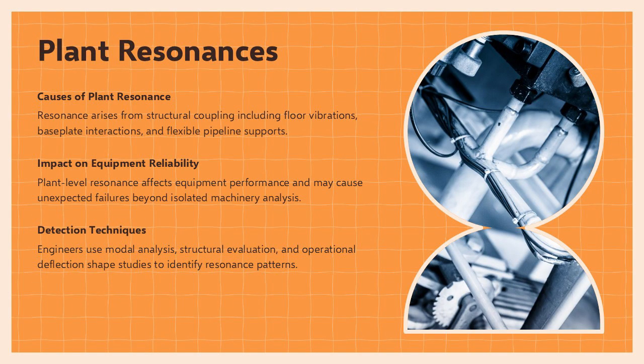Plant resonances occur within large industrial installations where equipment and interconnected structures share vibratory pathways. Even if individual components operate correctly, the combined system may produce unexpected resonant frequencies due to structural coupling. This includes floor resonance, baseplate interactions, pipeline support flexibility, and equipment-to-structure feedback loops.